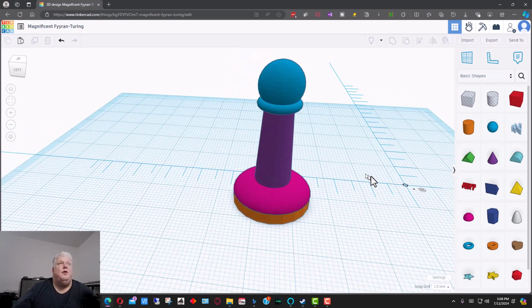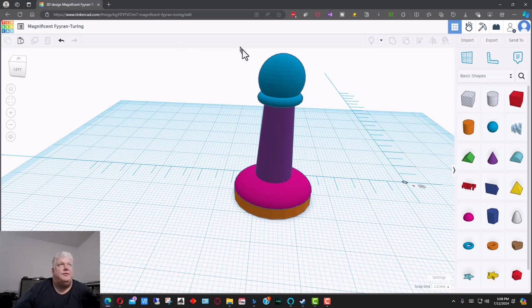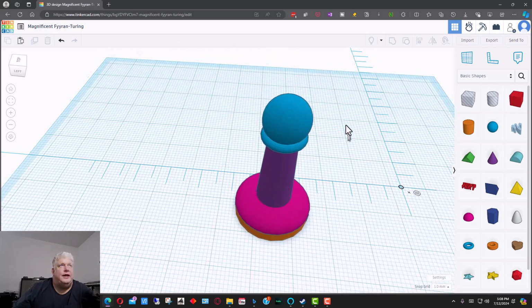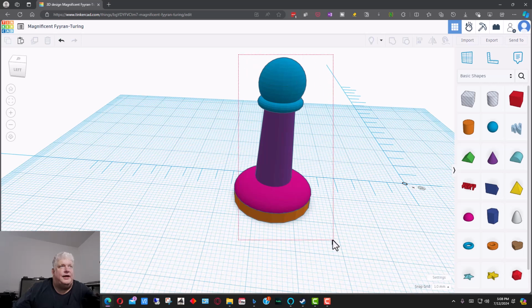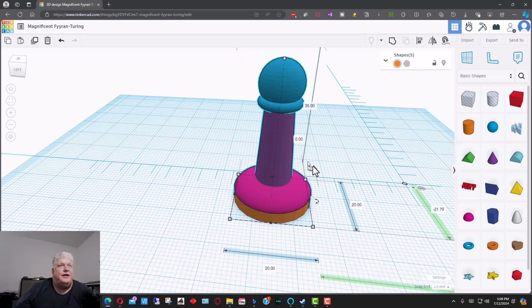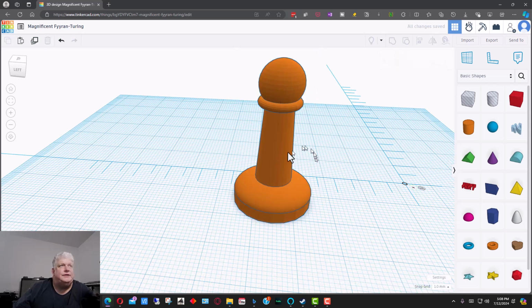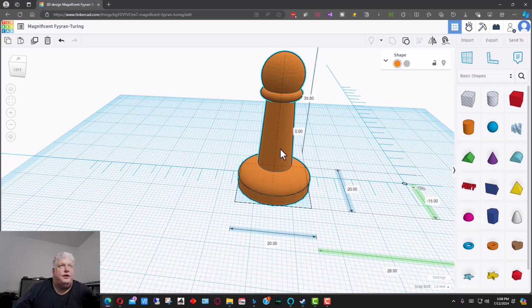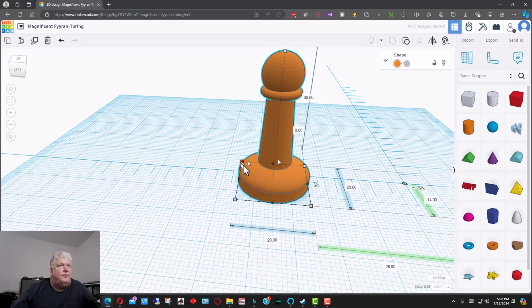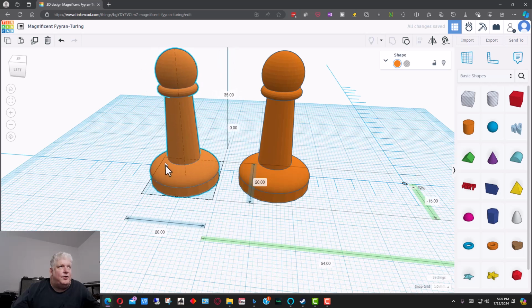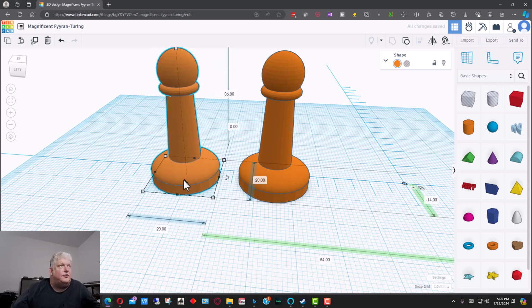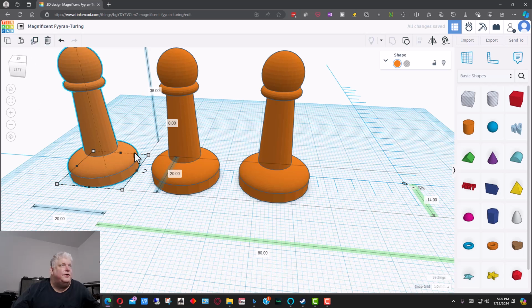All right, so there's one other thing we can do. Once again, we can click and drag so that we get everything selected, and we can group. And if we group, let's click on the workspace. It makes them all the same color now because they're all one unit. And we can actually move this around. If we hit Control D, we actually copy it, and then we can drag one out here. And so we could hit Control D, or we could hit this duplicate over here.